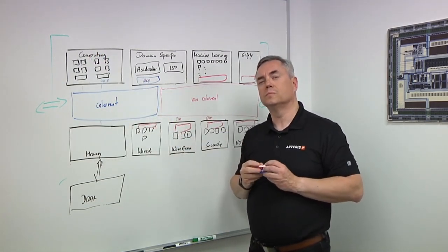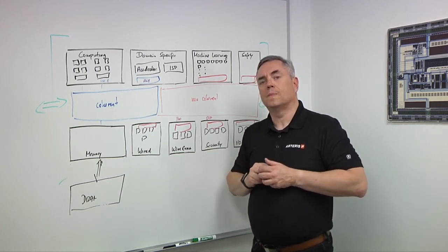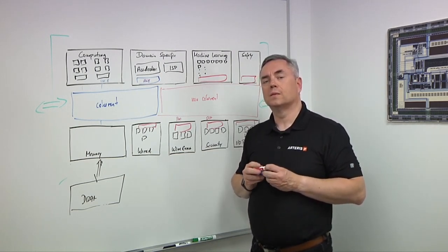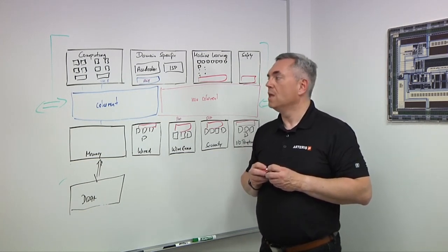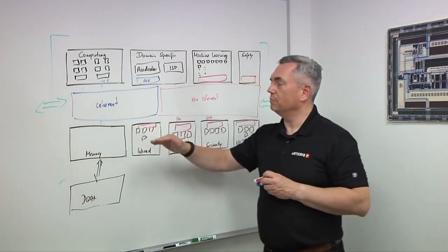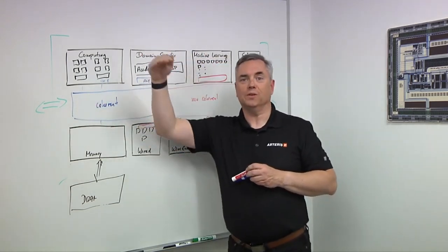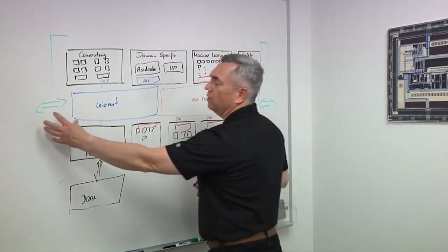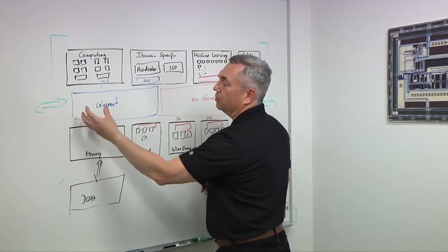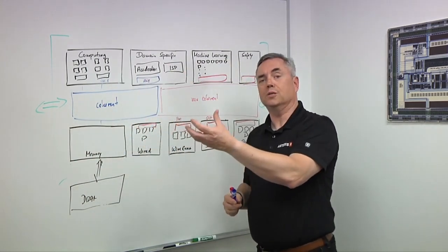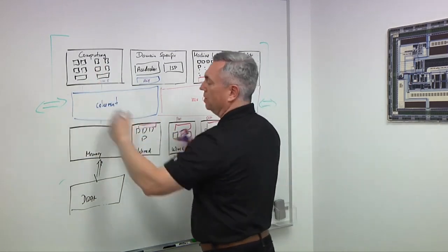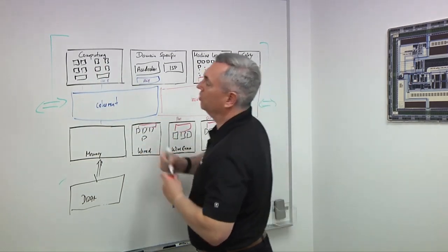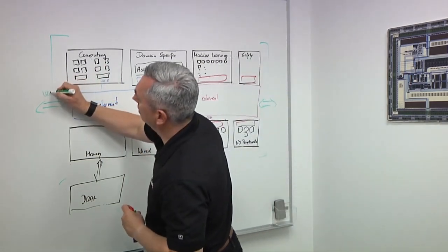So, what happens when you get into, say, a difference between a planar chip versus 2.5D versus 3D or some fan out, fan in? You've got all these different possibilities that are out there these days, and each one is a little bit unique. So that's a challenge kind of stacked on top of it, pun intended, where you have the potential product management requirement that all of this has to go across chiplets. So you have a chiplet interface here. So you may go over UCIe between them.